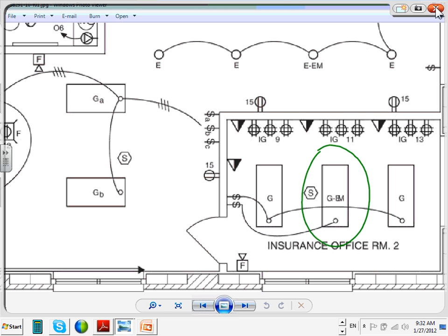So what they do is they have a sensor. They take a voltage from the circuit breaker ahead of the switch and bring it to that relay. The relay is just looking at the voltage coming out of the panel. Is the voltage there? Yep, stay as is. The minute it loses the voltage from the panel, because somebody turned the circuit breaker off, or a storm took down the transmission or distribution line, there's a tiny little relay inside that switches you to the batteries. So it's called an emergency fixture with battery backup.